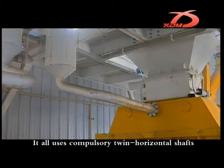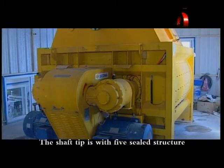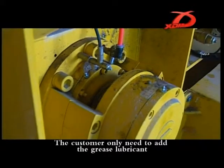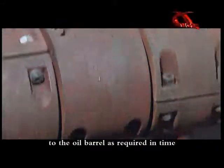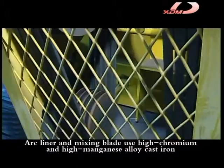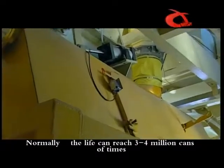It all uses compulsory twin horizontal shafts. The shaft tip is with a 5-sealed structure. The shaft tip supporting and the seals separate each other. The customer only needs to add the grease lubricant to the oil barrel, as required in time. Arc liner and mixing blade use high chromium and high manganese alloy cast iron, which is wear resistant. Normally, the life can reach 3 to 4 million times.